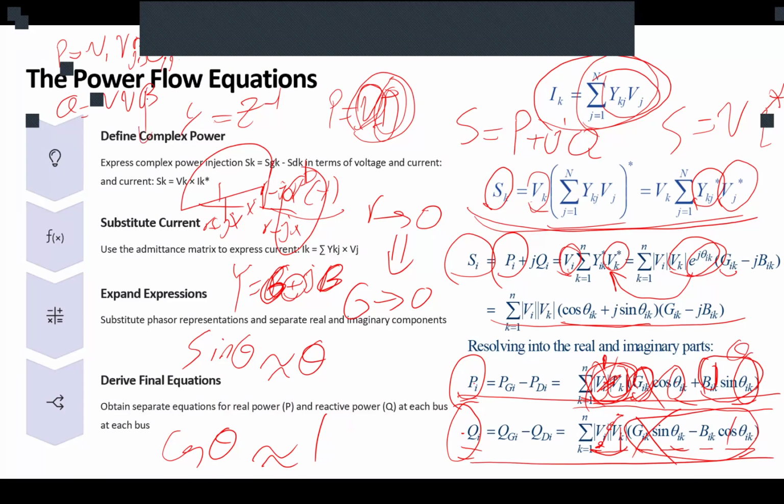These are solid, these are constant numbers. If these two are very close to each other, that means what actually changes P is the variation in theta. And here, the only variable that we have is these two V. So Q is a function of variation in voltage.